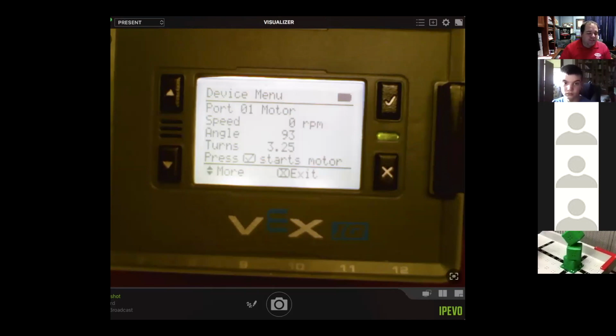The gyro is a little bit harder to read because the gyroscopes naturally reset. It feels it turn, and it gives you that turn, and then it goes back to 0. So it's a little hard to watch that on the screen. You can get some pretty good ideas if you're watching it live, but you're not going to be able to turn it, leave it sit, and then see that because it resets getting ready for the next turn reading.